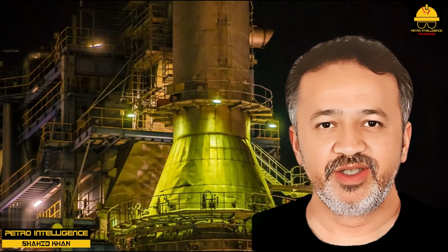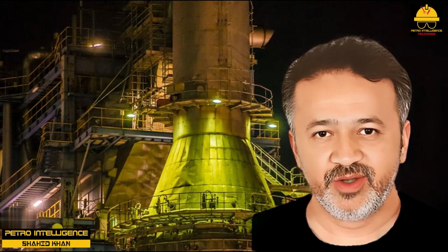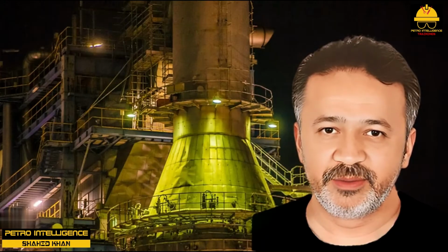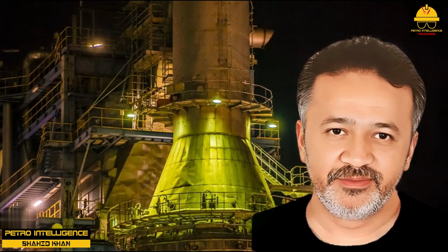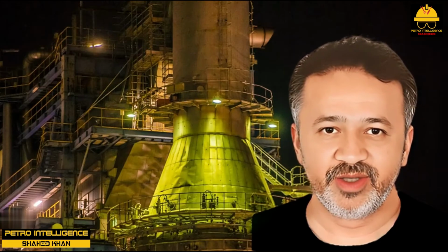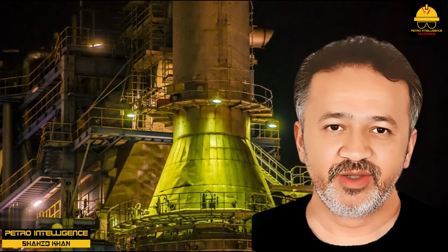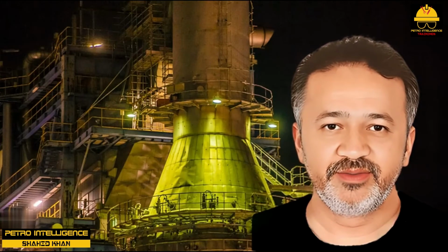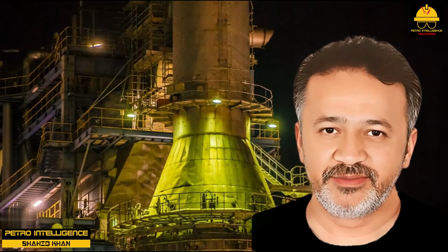The metallurgy of thinned carbon steel convective section tubes is not designed to withstand high temperatures. The fins will become oxidized and, when cool, may become brittle and thicker than before, thus restricting flue gas flow. The convective section tubes themselves will become warped and bent and thus restrict flue gas flow still further. Just such a thing happened as a result of another well-intentioned but misguided attempt to improve fuel firing efficiency by reducing the oxygen content of flue gas in a fired heater.